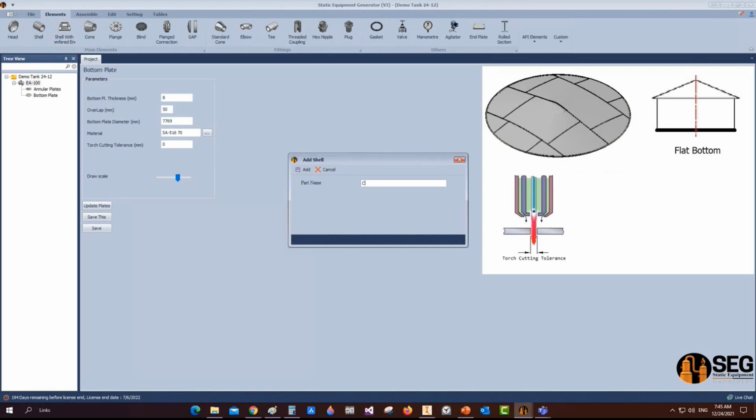Yes, just one doubt from Hyderabad. This bottom plate you have shown, sir, is overlap type, no? Instead of overlap, if you put some gap, and below that a stiffener plate is also there sometimes, a butt joint, can we make that type of bottom plate also? By defining the overlap value as 0. Yeah, you can define it to be 0. And then below that a stiffener plate is also there, sir. A 50 mm flat stiffener plate.